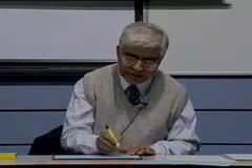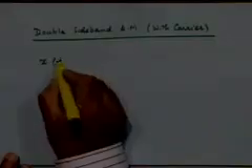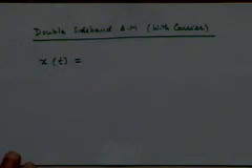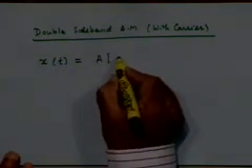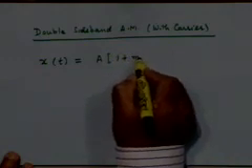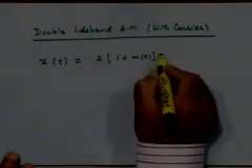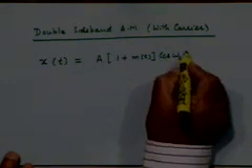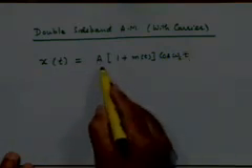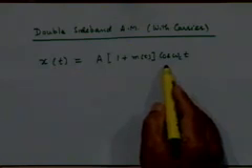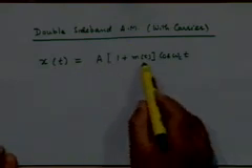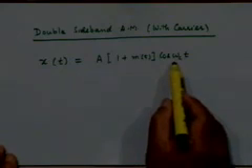Right? So basically, what we are saying is that in this case, your transmitted signal x of t would of course contain the part that we were transmitting earlier, but we also put in a carrier component. So it looks something like this. Right? As you can see, the second term is precisely the same term that we had earlier, right? A times m of t times cosine omega c t.